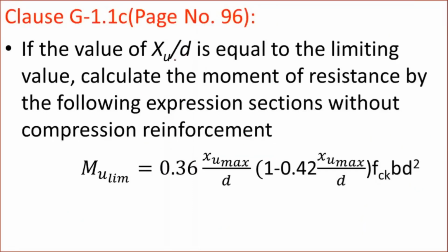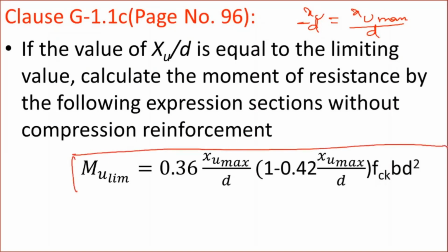Okay, see the next one. If the value of Xu/d is equal to the limiting value, that is, Xu/d is equal to the maximum value Xu,max/d, both are the same. So if Xu/d equals Xu,max/d, then we have to use this expression to determine the value.